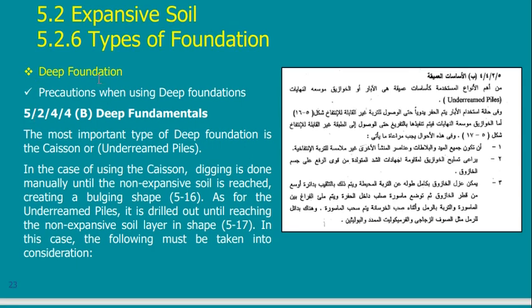Deep foundations, piles, we said also that they are not good. Why? Because once the expansive soil starts to expand, it expands to the top, to the right, to the left, everywhere. So if I have piles, then the expansive soil will exert horizontal forces on the piles, and it may crack the piles or induce additional horizontal forces on the pile.